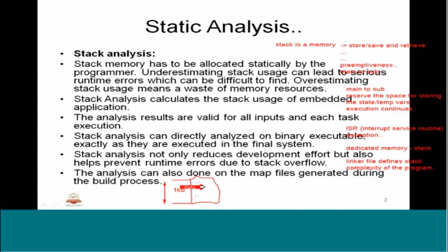So typically in the embedded industry they suggest the designer have at least 50 to 75% of usage, so that there is 25% of stack as a buffer. That is the standard they imply. Even for memory they recommend like that. Stack usage should be reserved, is what they specify.